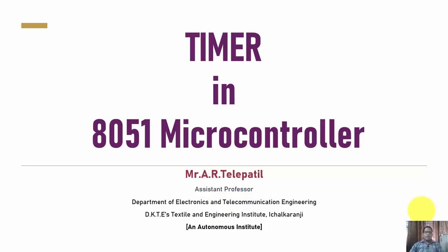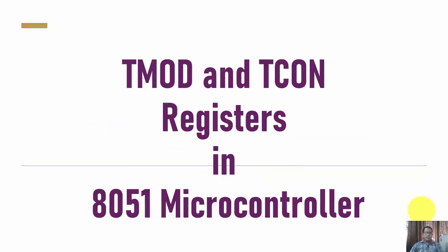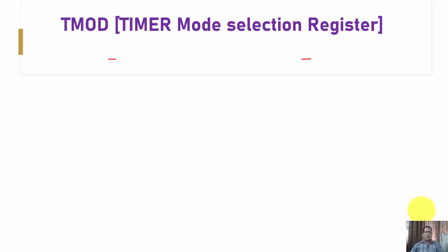We are discussing the timer section present in the 8051 microcontroller, and in this video we are going to talk about one of the two important SFRs associated with the timer section of the 8051 microcontroller, that is TMOD, the Timer Mode Control Register, and TCON, the Timer Control Register. So let's begin. When we talk about the TMOD register, TMOD stands for Timer Mode Selection Register, right?